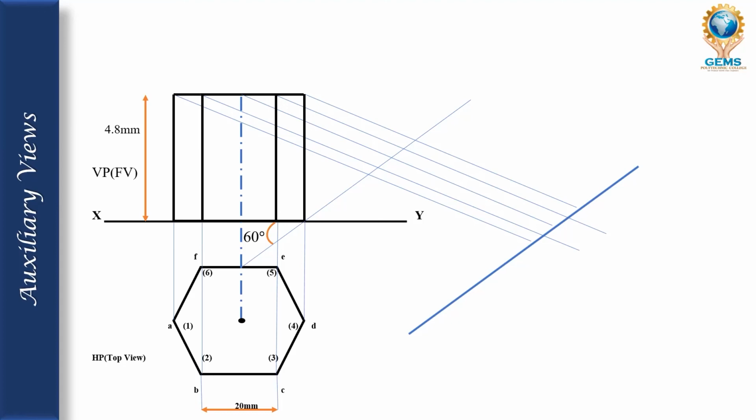Whenever you are drawing machine drawings or any objects or components, or mechanical engineering drawings, try to use a roller scale or drafter. But my suggestion, the best option, one and only, is the drafter. If you use the drafter, there is no need to go for 90 degree, 60 degree like that. Take only the 60 degree, draw it, and you can draw a perpendicular line easily by keeping the drafter at the same angle.